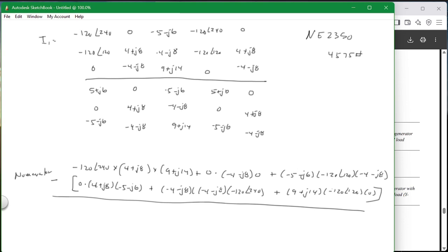You don't use it in industry, and we're not going to use it on the Rubik's project, because those things get jostled around and those wires break and you've got a mess. So anytime you use solid wire, it's for short-term bending and making something, but don't ever depend on it. Except big wire. Big solid wires don't break. But little solid wires tend to break. And every time, when you least expect it, it'll break. So it'll come loose or whatever.